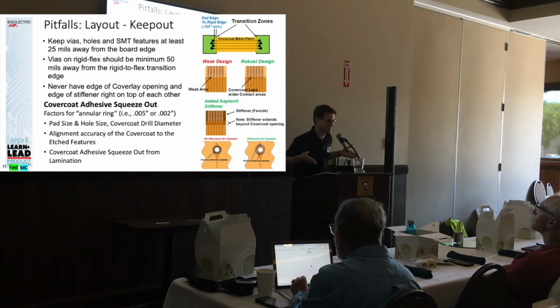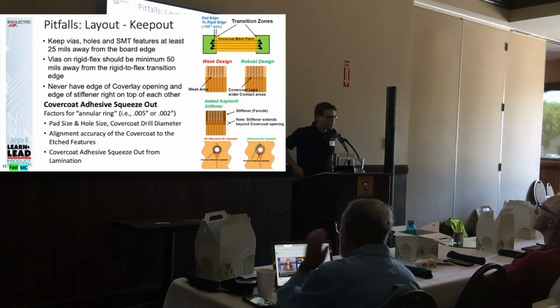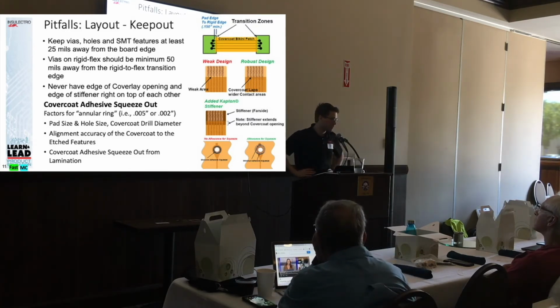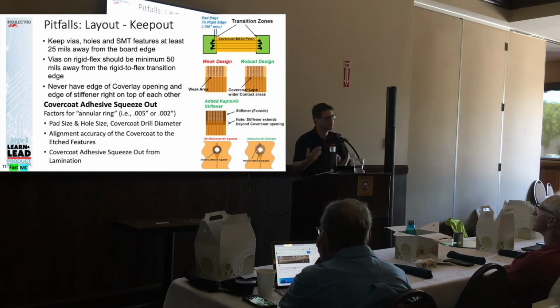Why don't you tell them the problem the acrylic is? Which problem? When the acrylic expands in the Z, what does it do to the barrel? It'll stress the barrel. It'll break it. It'll not just stress it, but it'll break it. You have other issues in chemical processing where you can get some crazy etchback if you don't account for it properly. It causes plating folds. The list can go on and on and on.